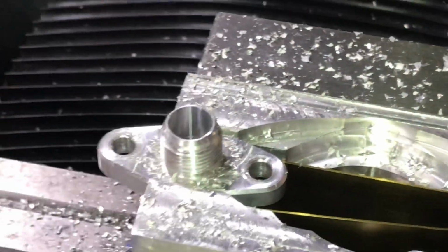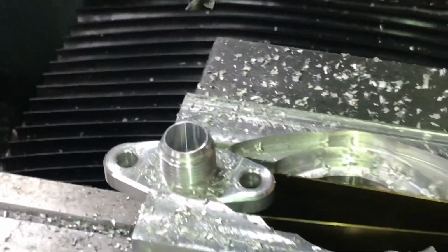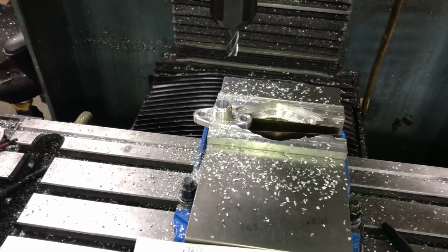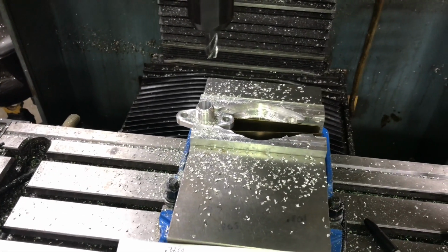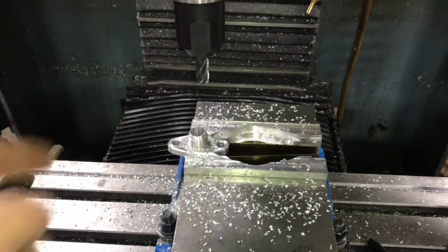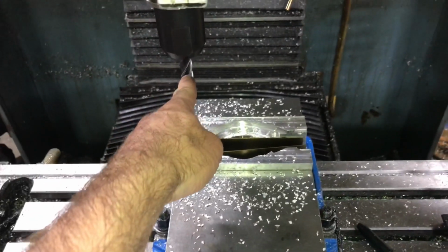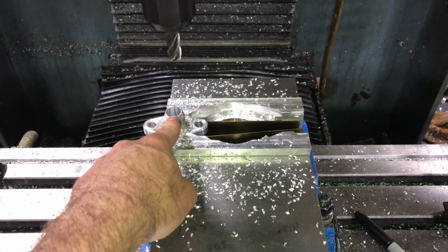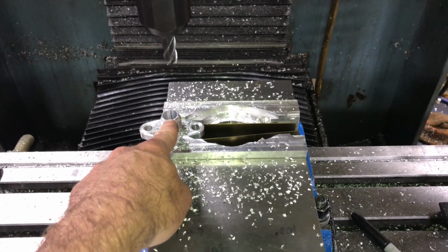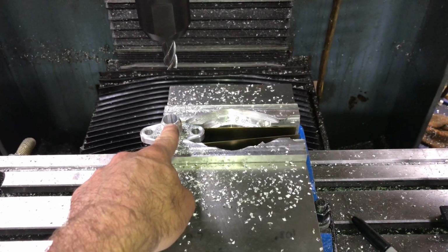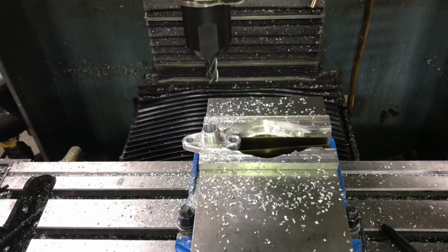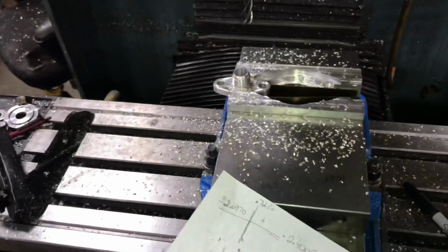And if you're worried about how much you cut on the inside, you could measure that again. I feel pretty confident because I set all the measurements that I wanted it to be, as long as what I entered in the machine was correct, which is the size of my tool, 1/2 inch, 0.3125, multiply that times 2, and that's 0.625 for diameter. If not, it's pretty close, so that'll work. I'm ready to take it out.